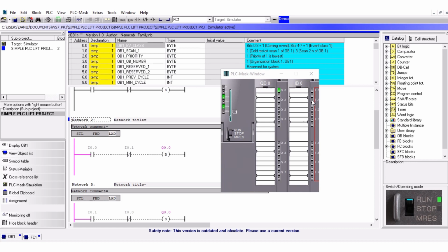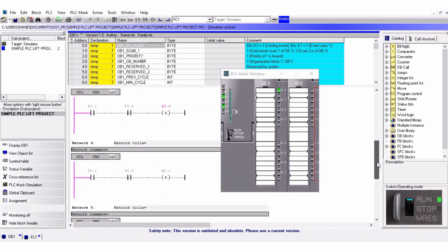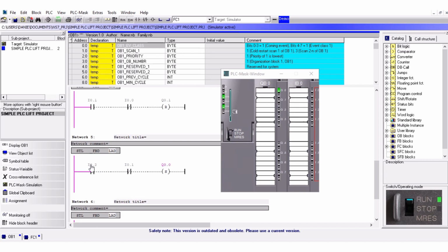So when you press again, like I0.2, I0.2 is where? I0.2 is here. If you press that I0.2, it will not change anything, because you remember the I0.2 is there to close this Q0.0. So you can close this other one, like I0.1, in order to go back to your Q0.0, or you can close this one to go on Q0.1. You see it? So that's it.